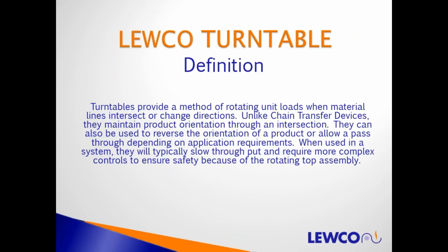The definition of turntable. Turntables provide a method of rotating unit loads when material lines intersect or change directions. Unlike chain transfer devices, they maintain product orientation through an intersection. They can also be used to reverse the orientation of a product or allow a pass-through depending on the application requirements. When used in a system, they typically slow down the throughput and require more complex controls to ensure safety because of the rotating top.